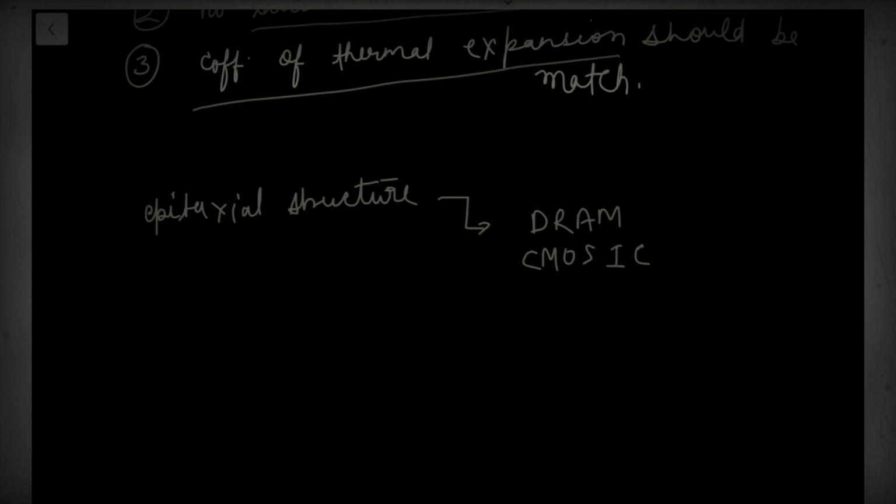Epitaxial wafers have two fundamental advantages over bulk wafers. An epitaxial layer on a substrate, often containing one or more buried layers, offers the designer more control of the doping profile in the device than is available with diffusion or ion implantation.